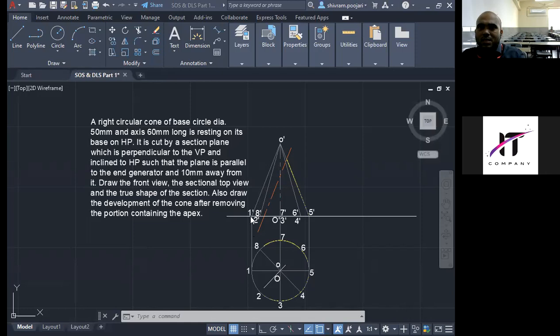You keep the roller scale here on an inclined line and then roll the roller scale. The roller scale has a calibration. See that calibration and roll it only for 10 mm. So when you roll it for only 10 mm, you will get this line. The line you are making should be long dash, short dash, long dash, short dash. Just draw it, come on.